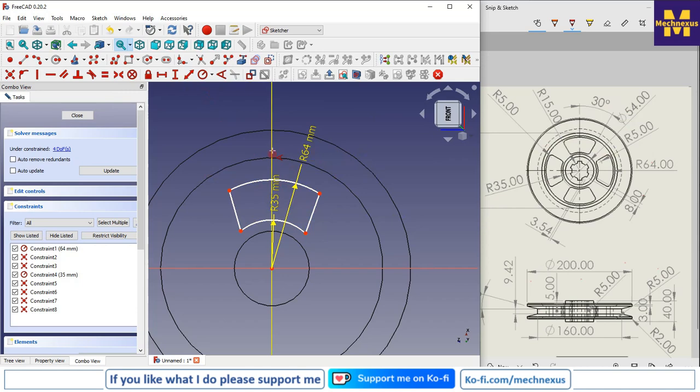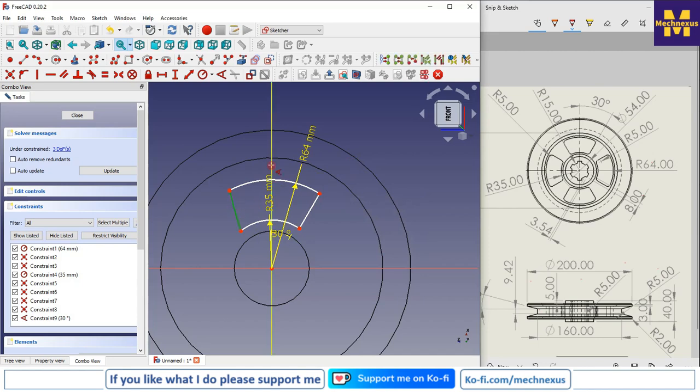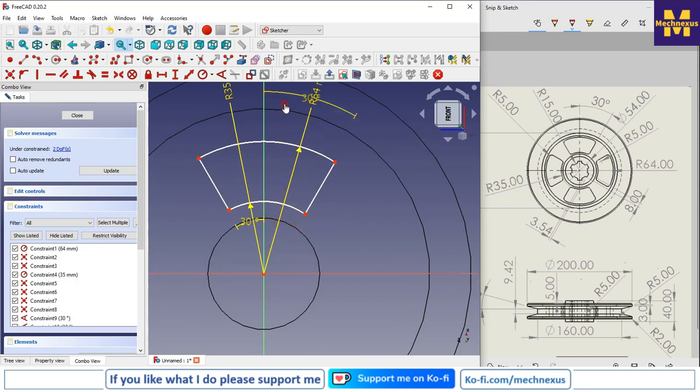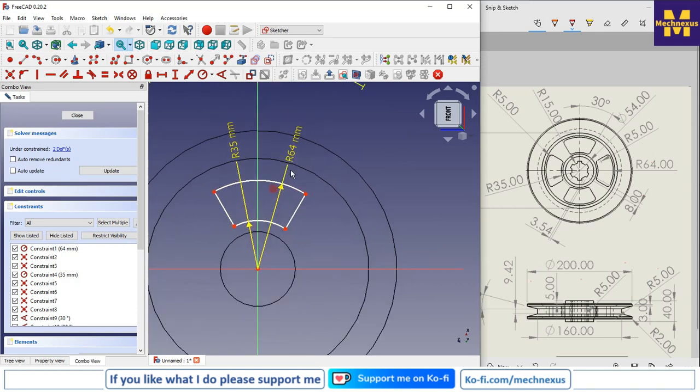So I will select the angle and I will give it 30. Same way this will be the 30. Now I will move my dimension outside. So now if we see, this is unconstrained and this side is also unconstrained, so we will make it constrained.